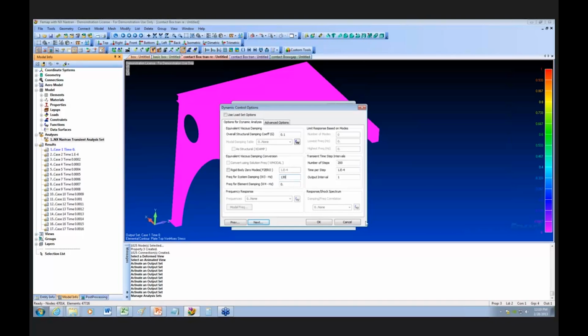But that's how you do dynamics and how you get a more realistic solution, and how you use engineering judgment. Okay. Also, what's important here is the time steps that it goes through. You also want to remember in your time steps that whatever frequency, if it's 130 hertz, that's 130 cycles per second. So it's 1 over 130, and then I divide it by 10 to break it up into 10 to give an idea of how many time steps you need. That's the world of dynamics, to make sure you capture that frequency and that you don't filter it out.